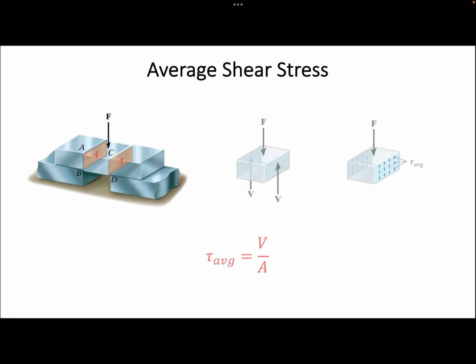As you will see later on, the shear stress predicted by this equation is much smaller than those obtained with a more precise investigation. However, engineering codes still allow it to be used for determining the size or cross-section of small elements like bolts, or for obtaining the bonding strength of glue joints subjected to shear loadings.